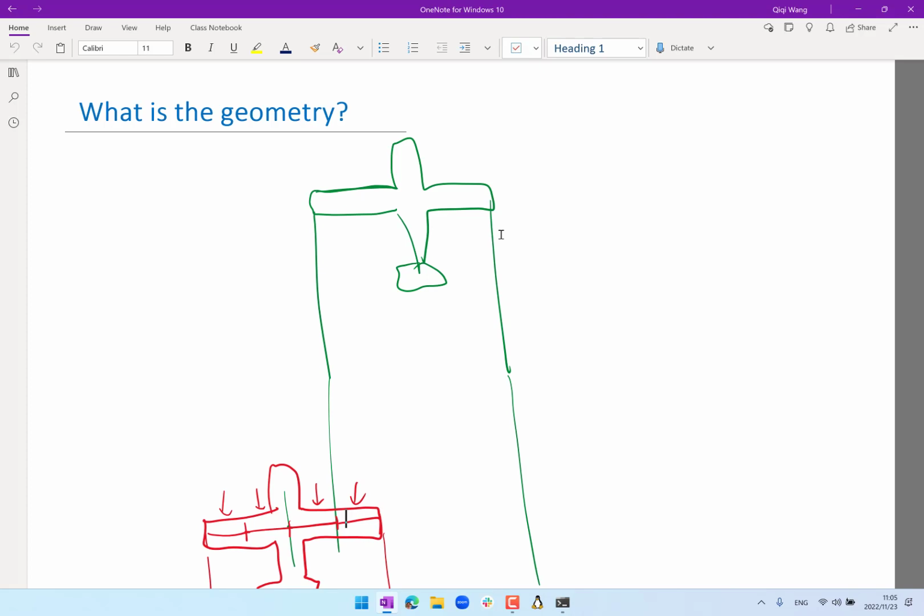Now you might have to redesign the wing such that wave drag is not a factor. Okay. Now, skin friction drag is easy to calculate. You just need to calculate the whole area and estimate the skin friction coefficient based on the Reynolds number. And you will see that at this Reynolds number, the skin friction drag is pretty flat as a function of the Reynolds number, right? So no matter if you base it on the chord of the wing, the length of the fuselage, etc., the skin friction coefficient doesn't really change that much. Maybe it goes up and down by 10%, but not much more. All right, so skin friction drag is pretty easy to estimate if the required accuracy is like 10-20%.